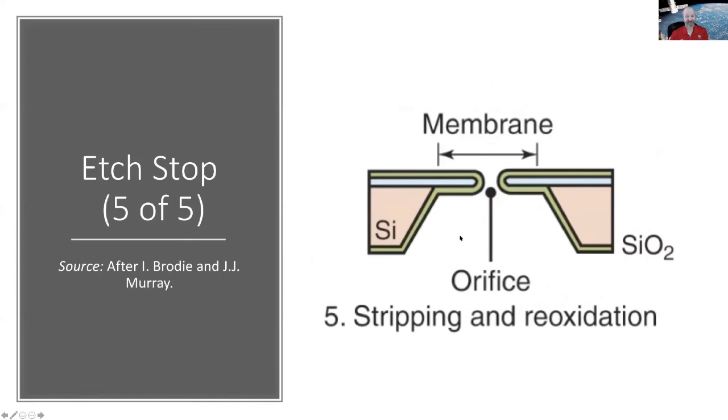So that's interesting, right? You can kind of think as a mechanical engineer, when would I want a hole in my membrane? You might want to actuate that membrane. It comes down like this, and then fluid jumps through the hole. Or you can leave just a stiff membrane the way it is with a hole in it, and you made a nozzle, right? So you can do lots of cool things, and you can control the size down to micron levels. So you can make atomizers and things like that, where you can control droplet size exactly, which might be good if you use it in an engine, right?